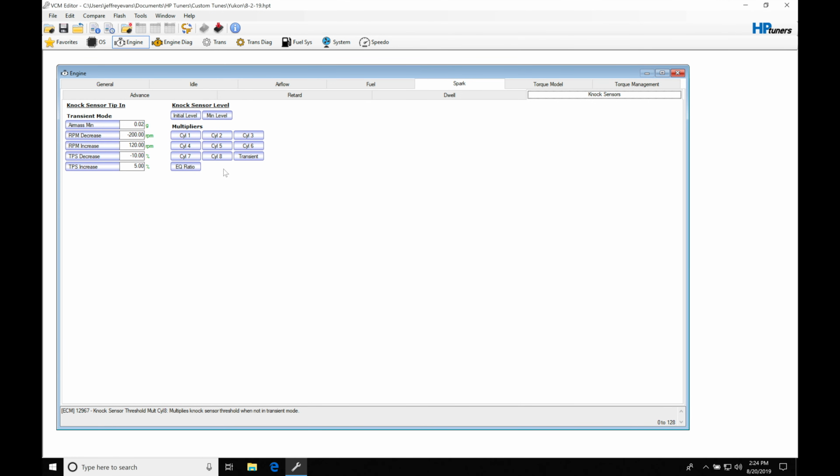So the way a knock sensor is going to work, it's going to be essentially a microphone. It's going to be mounted to the block, and as a knock event occurs, there's going to be small pressure waves that are going to be transmitted through the block. The knock sensor is going to act as a microphone, and it's going to send out a voltage output based on the amplitude or the audible level of the knock. Now, knock can occur and we can't audibly hear it with our ears, but a knock sensor can pick it up. There will be situations where we actually can physically hear it with our ear, and it's going to be a pretty severe event in that case, and then it'll also be reported in that manner by having a higher voltage output.